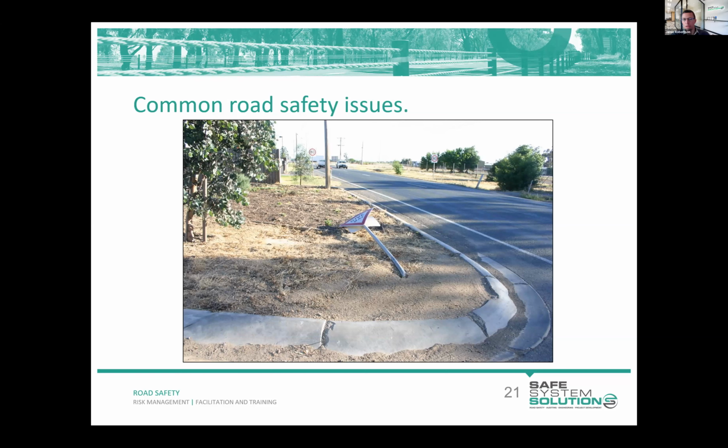Yeah, you should. If the signal phasing was such that the movements couldn't occur concurrently, then the risk is largely addressed. There should be some flexibility in intersection design. It would be desirable to cater for those movements to occur concurrently in case the signal phasing were to change in the future. But I suggest that you do look at the signal phasing as part of your assessment of risk of that issue. Thank you.